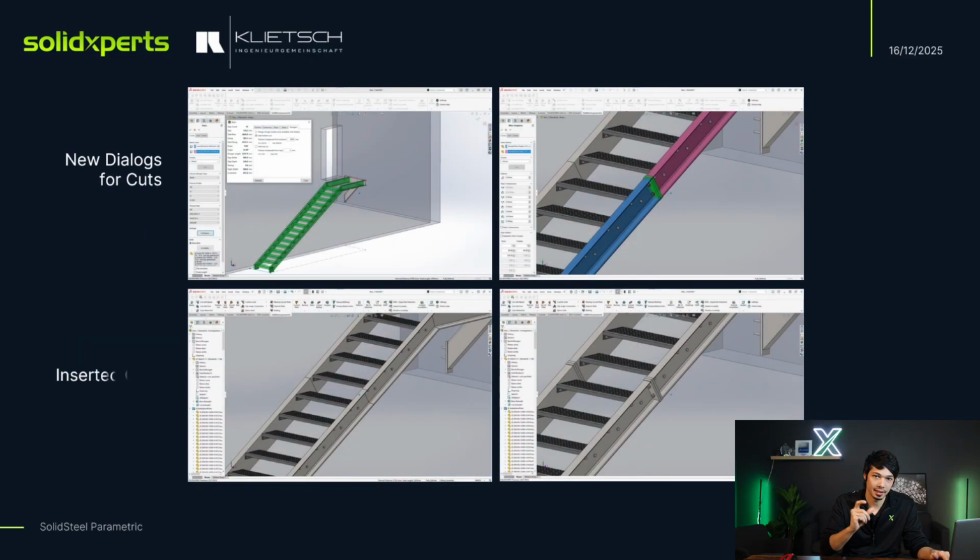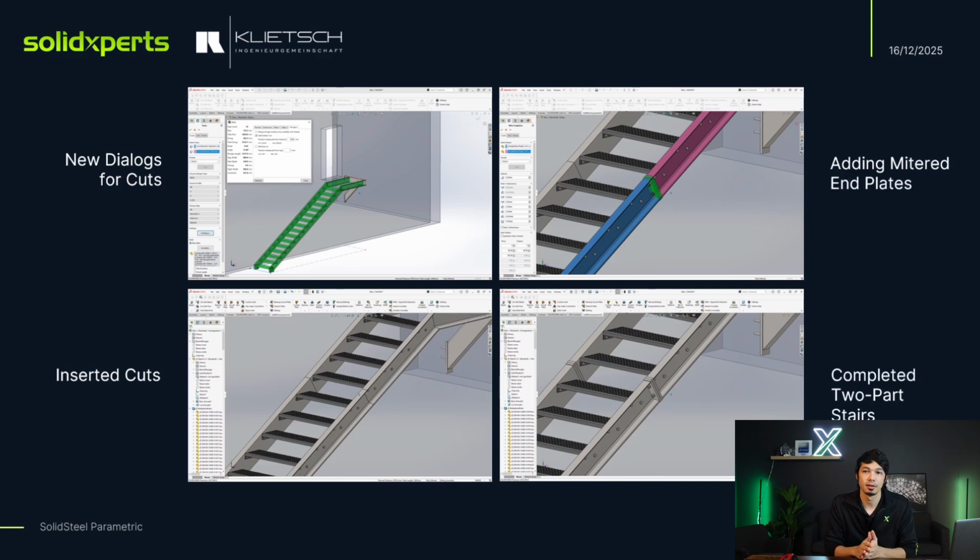Taking a look at that a little bit closer with some screenshots, you can see the cut dialogues have been fully redesigned with a cleaner layout, giving you a better preview of what the end result is going to look like. Obviously, we have some easier mitering and then faster insertion of our end plates and other cut components. So once again, more improvements that are especially noticeable within the stairs workflow.